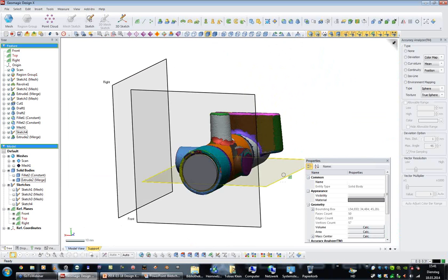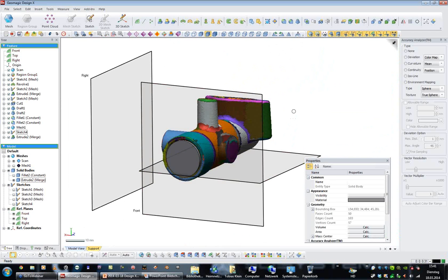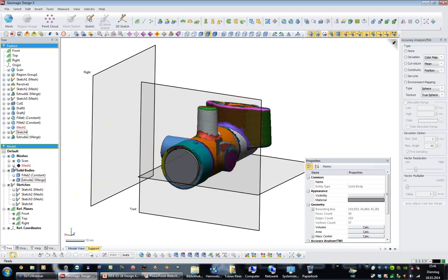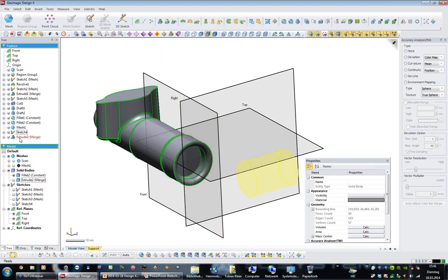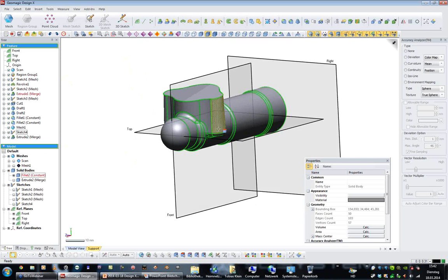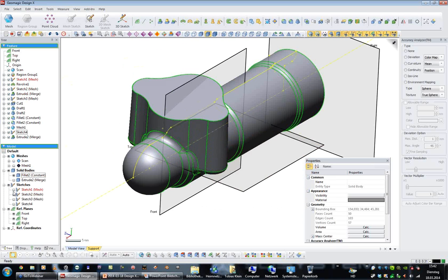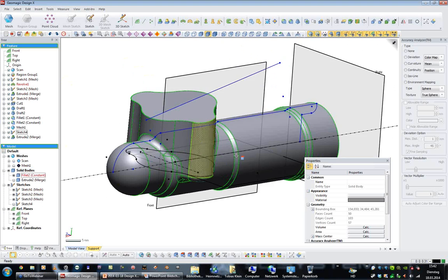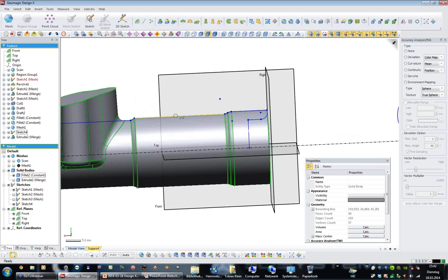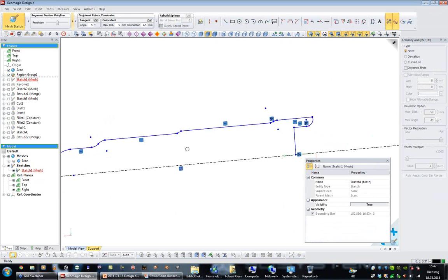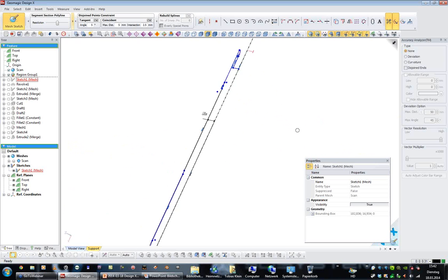Okay. With the software, can we make dimension control for scanned parts? We can get the dimension of the part out of the scan. That is the situation. And once we have this CAD, we can alter the dimensions, of course, because we have everything parametrically here. For example, for my first revolution, I want to change that diameter. So I just double-click this sketch for the diameter, and I can just get the dimension here. So it is